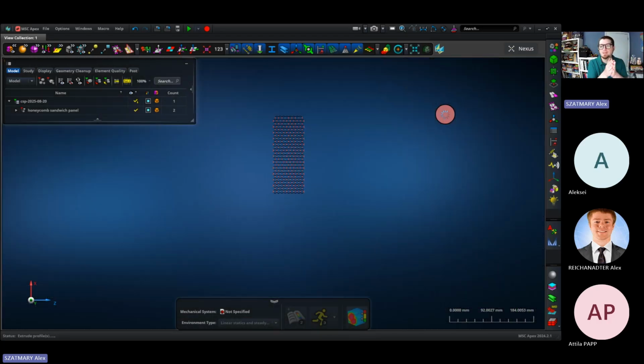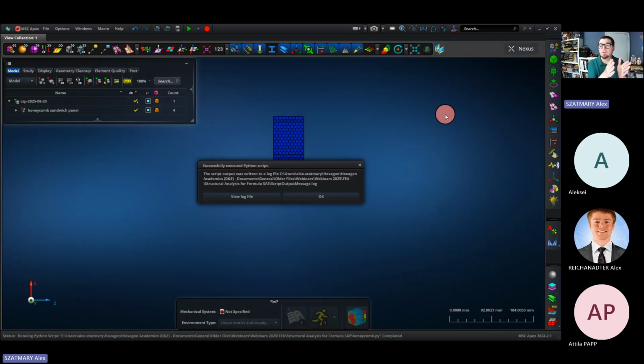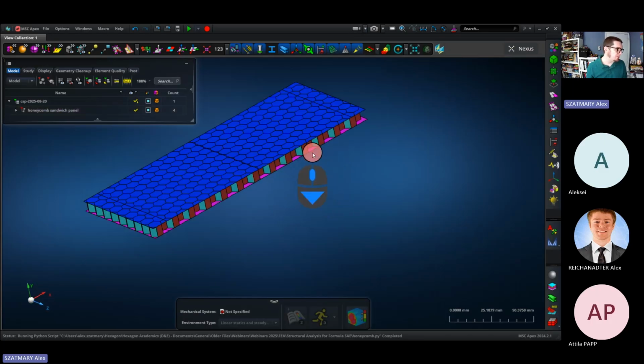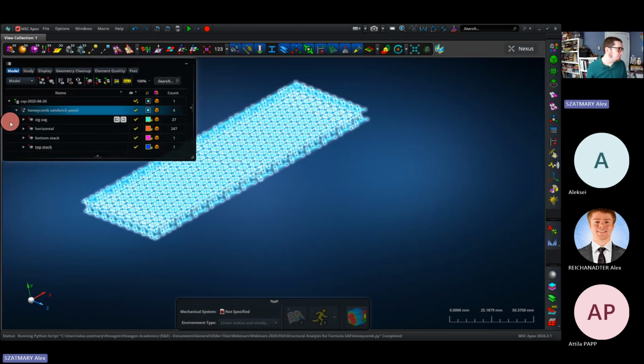So honeycomb is made by taking multiple layers and adhering them together in certain ways such that when you expand it, that honeycomb shape is formed. And because some layers are adhered together, they have double the thickness of other layers or other faces. So those faces that are in the L direction, like this one, are going to be twice as thick as the ones in the W direction.